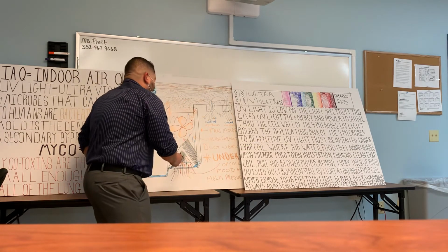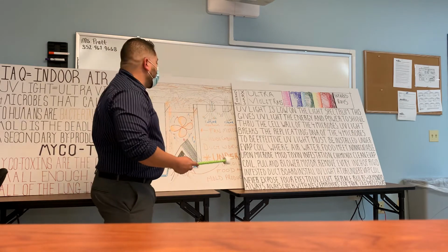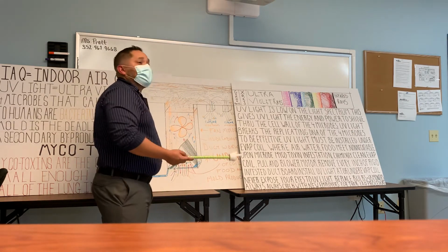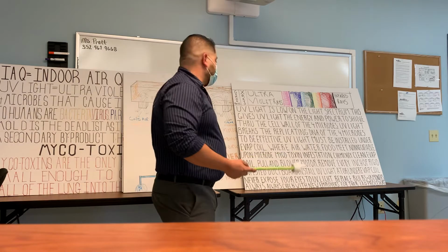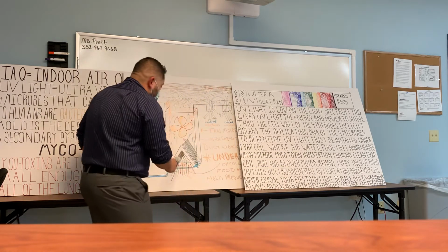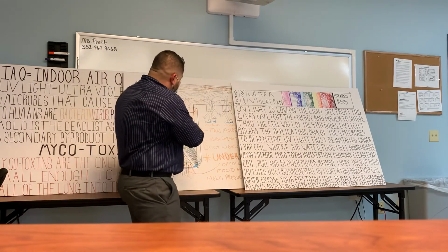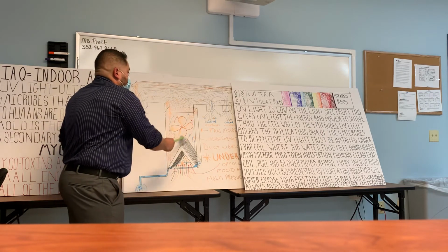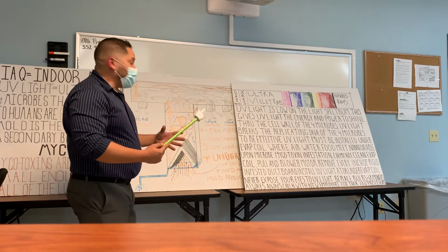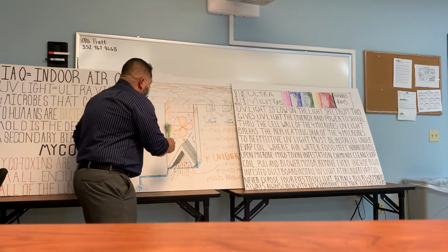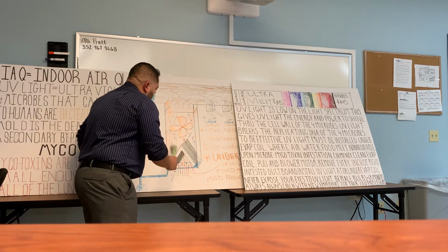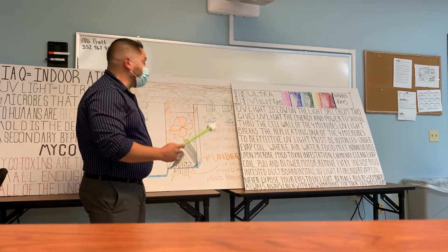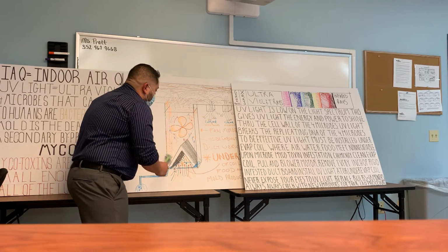But you'll find some units where someone just moved in, and they didn't realize the people that lived there before had 3 dogs. Never changed the filter, never had a filter. So we're going to pull and chemically clean this coil. We're going to pull the blower motor out. It's going to be sanitized. The squirrel cage is going to be pulled off the motor shaft itself, sanitized. We're going to sanitize the inside of the actual air handler. Sometimes you even need to take all the insulation fiberglass out and reline it.